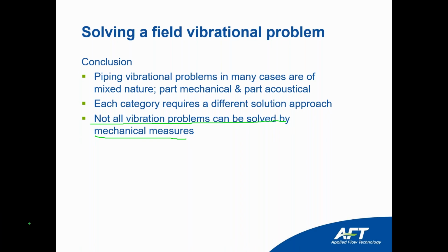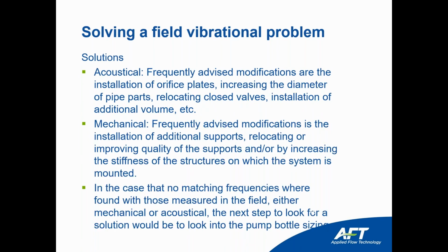So changing the supports in the system when you have an internal acoustical resonance will not solve the problem. You will have the high vibration, the high forces, because the problem is caused internally. So in this case, this is why PFA is so important, because you have to determine whether the problem is acoustical or mechanical.